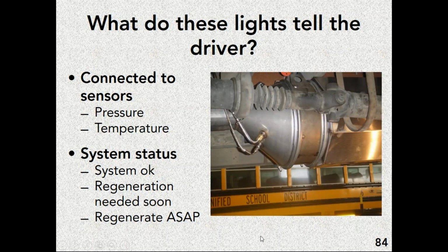All right. It's connected to the filter using those two plugs. One of those is measuring the temperature across the filter, and one of them is measuring the pressure across the filter. Now, the pressure is measured because the higher the pressure differential gets on one of these, the more plugged it is, and the more it needs to be regenerated. The temperature is measured because you need to make sure it achieves the right temperature for regeneration to be successful. So both those things are important, and both will be monitored and relayed back to the driver of this device.